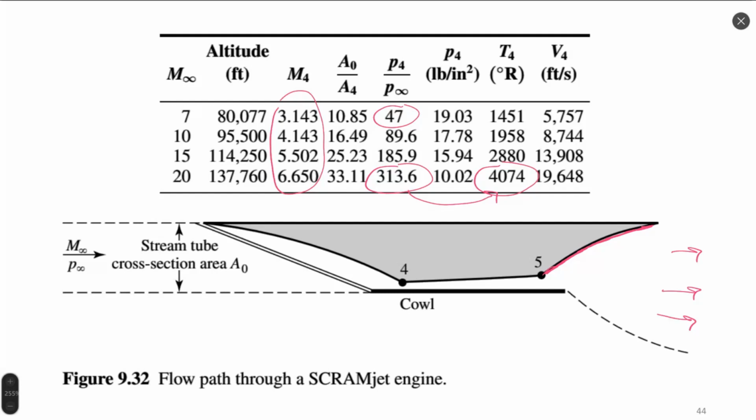You can observe such a problem in numerical simulations, quite typical. Especially, many of you will also see it when you simulate work 2, when you try to simulate your diffuser. If you make too small an exit section of flow, you can also create a condition of thermal block when temperature increases, pressure increases in the exit section so much that it stops.